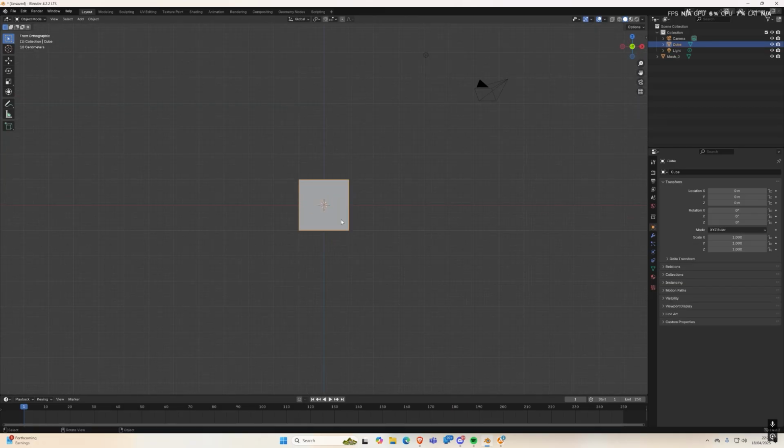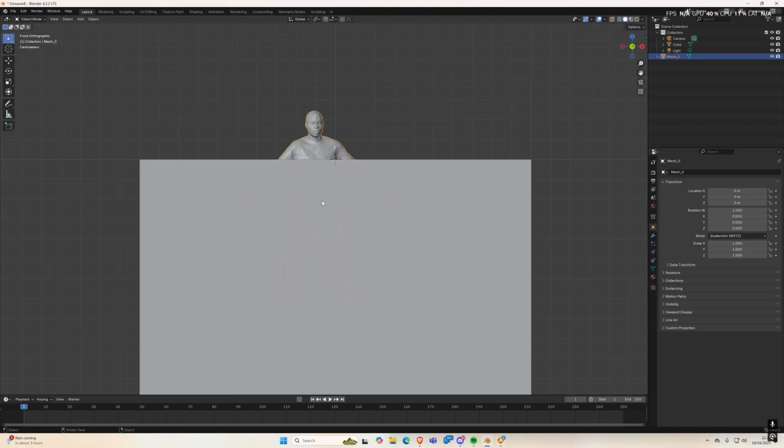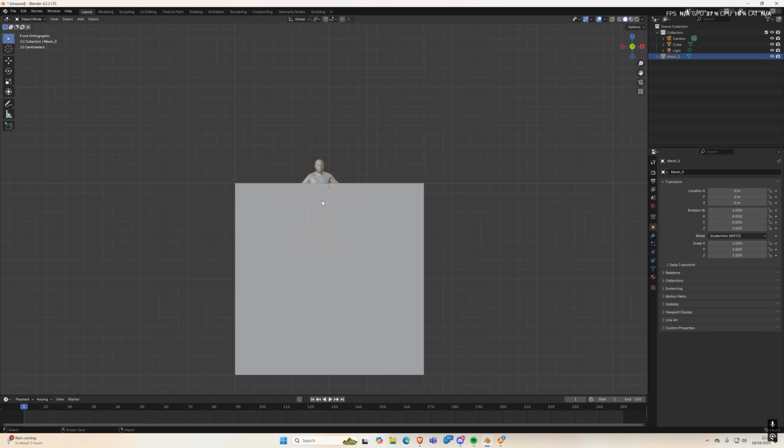Then I'm going to grab this cube. I'm going to press shift tab, grab Z, so first of all it snaps to grid, and then I'm moving it on the axis. Now come back out from the snap to grid view, which is shift tab on a window. Select this guy and press number 1, and I'm now focused on him.